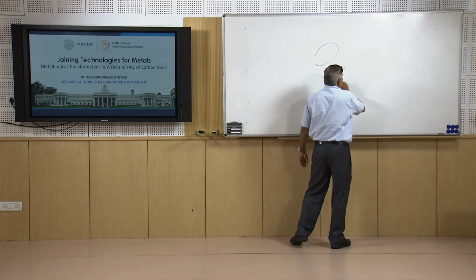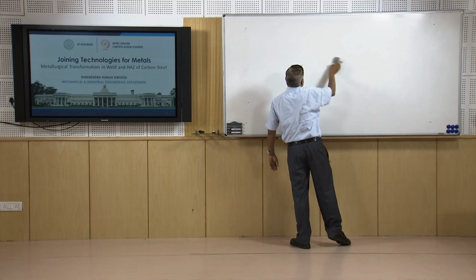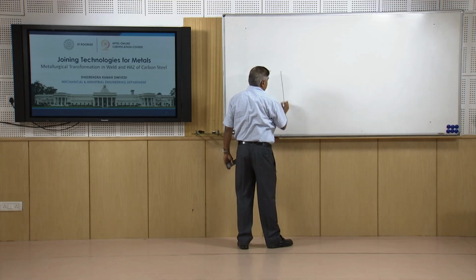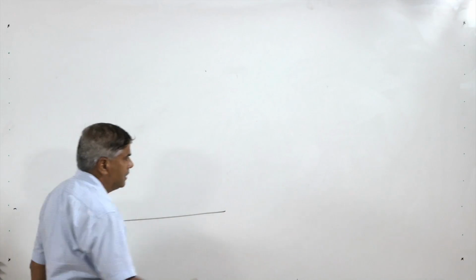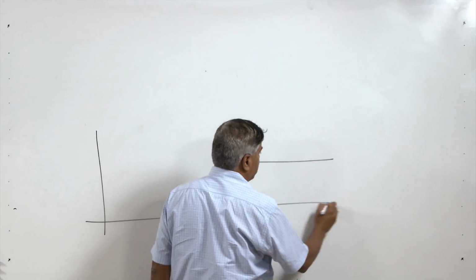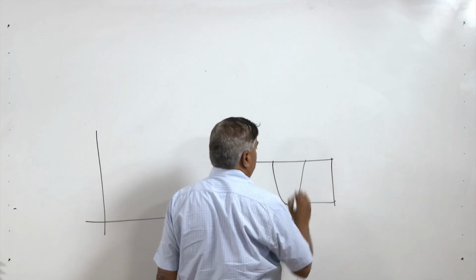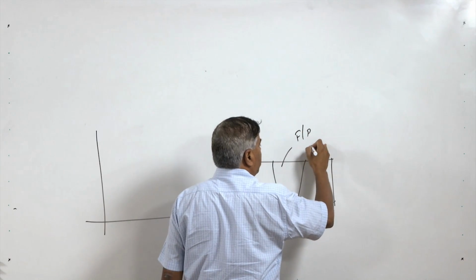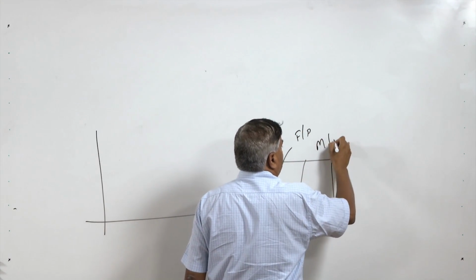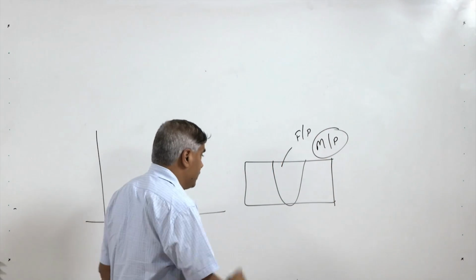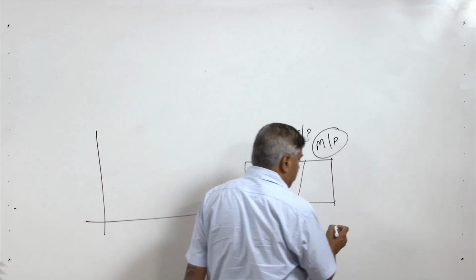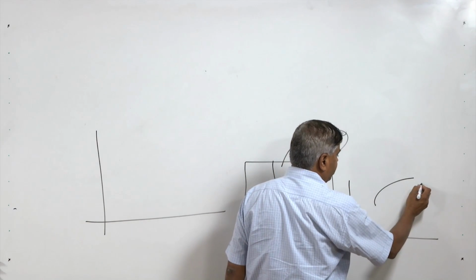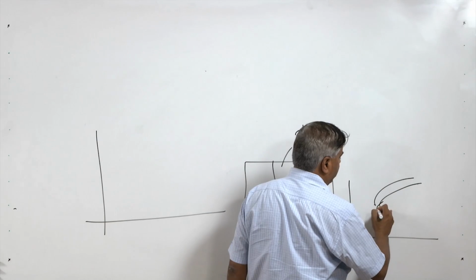So far we have not talked about the weld. In general, the weld experiences a much higher heating rate as well as cooling rate, and that is why, as per the carbon content in the steel, mostly it forms either ferrite or pearlite, or it may form martensite and pearlite in the weld, and that is governed by the composition of the steel. So, for that we need to see the CCT diagram for that particular grade of steel.